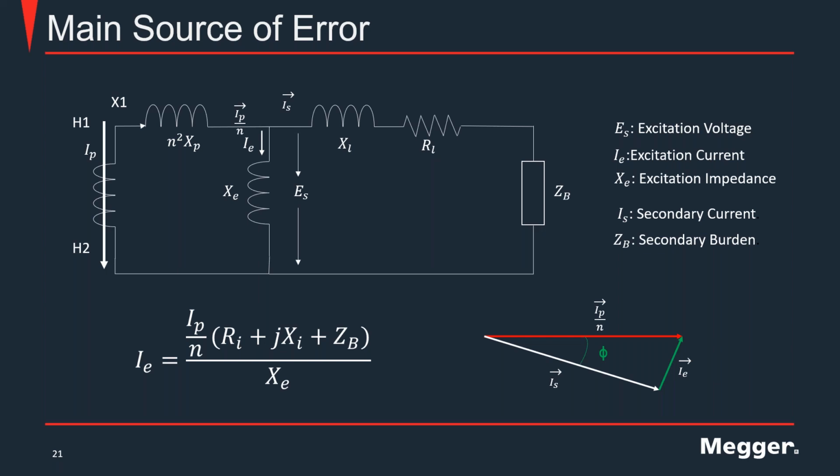Okay, to answer this question, I guess we first need to understand why we would get a magnetized core in my CT. So in practical terms, we can say two main scenarios, right? In service, that would happen if a large primary current circulates, and that is obviously in case of a fault.